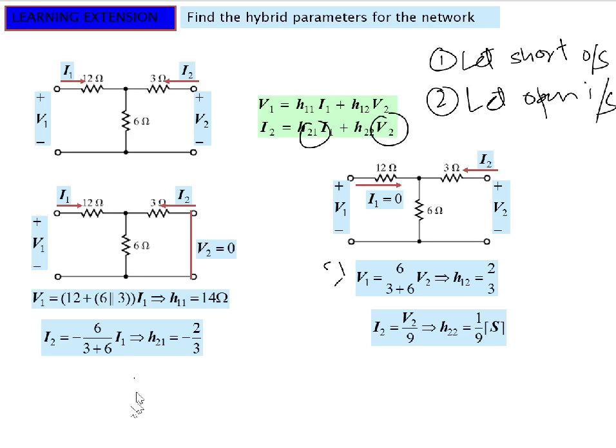Let's say this is our first current and some part of it is flowing in the second network. So the second current would be I2 is equal to I1 multiplied by the branch in which it is not flowing divided by the total path. So we will use this current divider rule here.